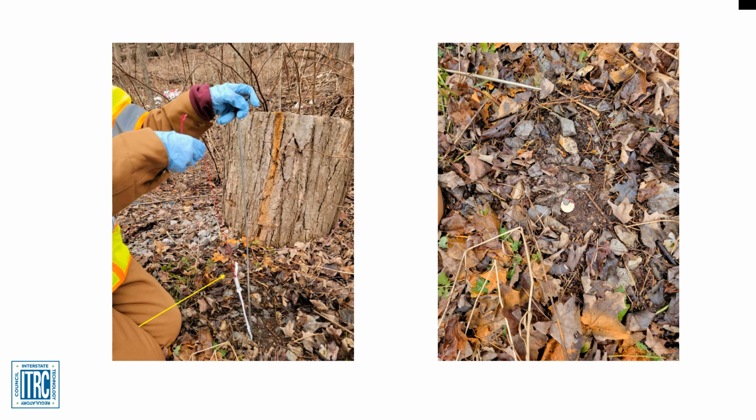The AGI sampler is then removed from the glass vial. The string is threaded through the looped end and secured with a knot. Next, one of the stainless steel insertion rods is placed into the dedicated pocket of the sampler, and both the rod and sampler are inserted into the boring, ensuring the module is pushed down to the target sampling depth.